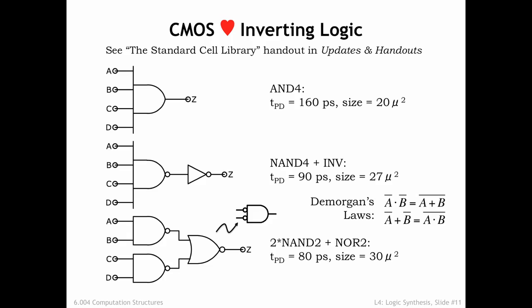The top form is the one we're interested in for analyzing the lower circuit. It tells us that the NOR of A with B is equivalent to the AND of not A with not B. So the 2-input NOR gate can be thought of as a 2-input AND gate with inverting inputs. How does this help? We can now see that the lower circuit is actually a tree of AND gates, where the inverting outputs of the first layer match up with the inverting inputs of the second layer.